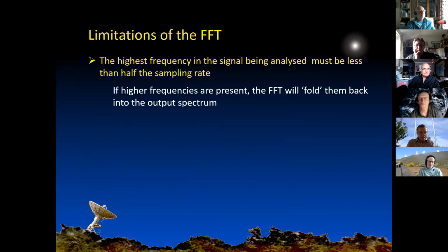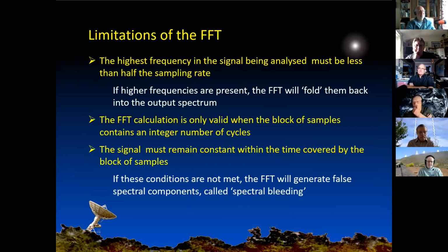Okay, so very useful mathematical algorithm, but it has its limitations. I've mentioned one already about the highest frequency driving the sampling rate. Two other important things is that the FFT calculation is only valid when the block of samples contains an integer number of cycles, which is easy to do if you've got a constant tone, but we want to use this with signals that contain lots of different frequencies.